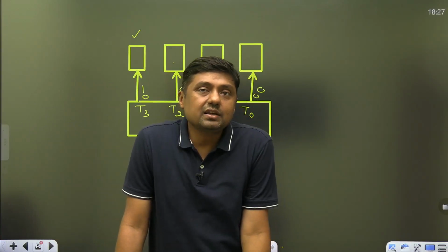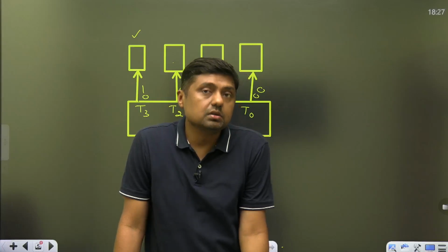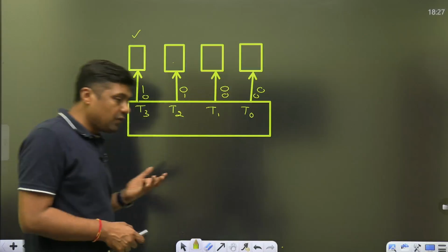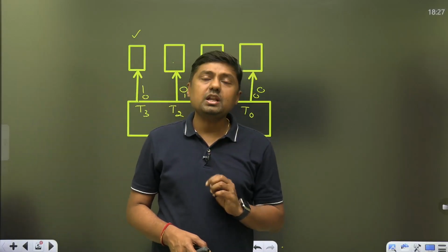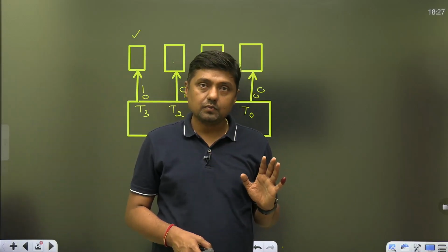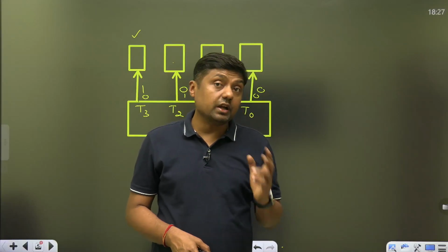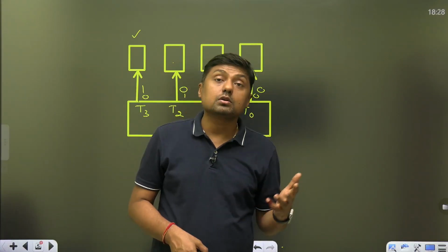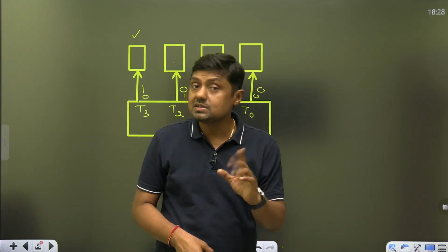Now, what are the disadvantages of this ring counter? The disadvantage is that we are using 4 flip-flops and we can generate only 4 timing signals. So it is inefficient, right? When we use the Johnson counter, you will get the idea that we are using 4 flip-flops and we can generate 2n, meaning 8 timing signals, guys.